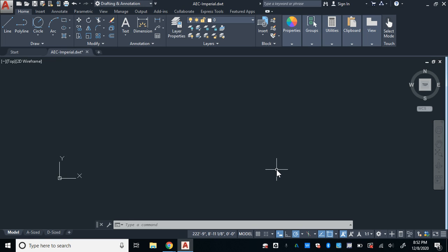All right, this is chapter 13.5, Architectural Project 1 Floor Plan. In the book, it states that you should use polyline, fillet, offset, and trim to complete this project. Once again, looking at the drawing, how should I tackle it? Looking at the dimensions that it gives you, all the dimensions are with respect to the outside portions of the walls, exterior walls specifically.